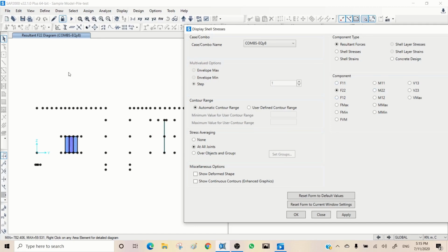Then the other option useful for you is section cut. So the load here on this wall is different in different areas. You have different axial internal forces. So how can you see the total axial force for this wall? You need to draw a section cut.